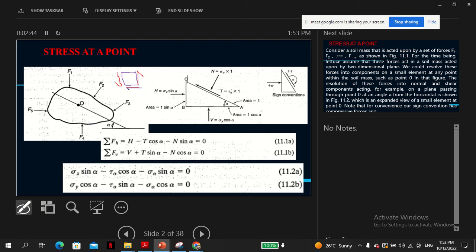What you should take away from there is that the presence of normal stresses ipso facto induces shear stresses. So when normal stresses exist, shear stresses have to exist. There's no question about that. All we are trying to derive here is the relationship, because normally when you introduce normal stresses, shear stresses will occur as a result. And what is that relationship? That's what you want to derive from principle.